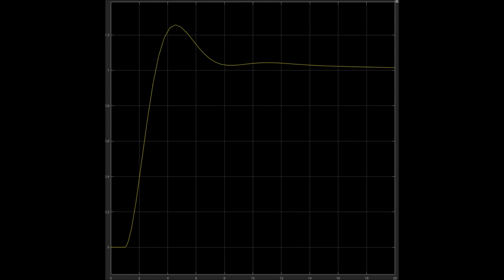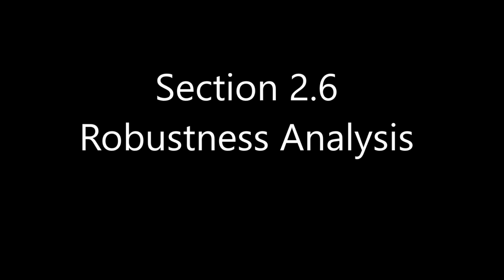We are able to eliminate oscillations and minimize the overshoot to about 25%, but overshoot was still present. We are able to minimize the ramp disturbance to 10% of the final output, or 0.1, but are not able to eliminate it based upon the controller architecture.